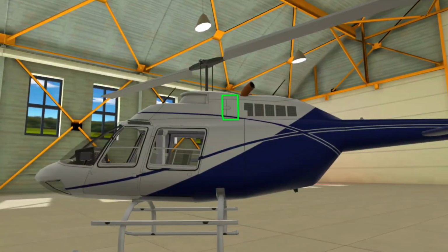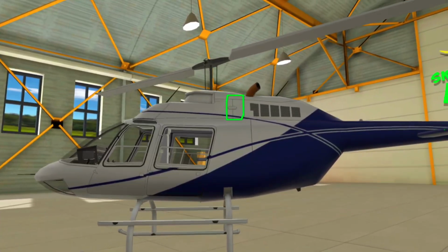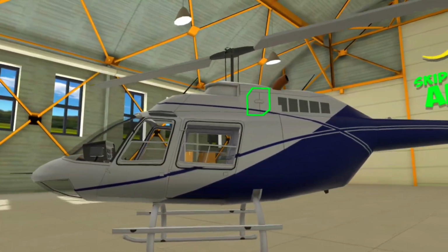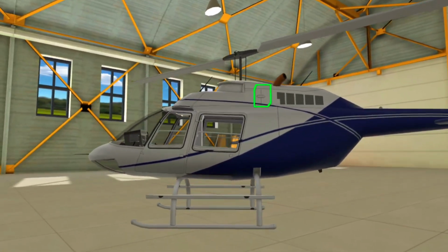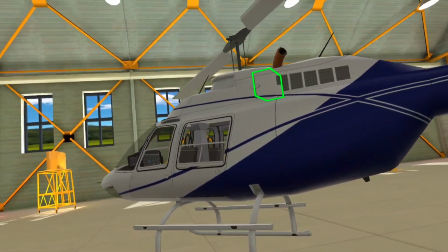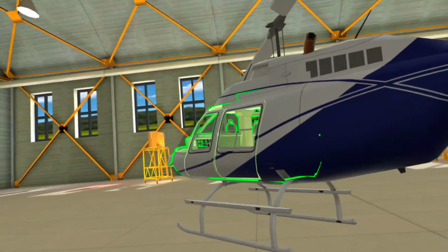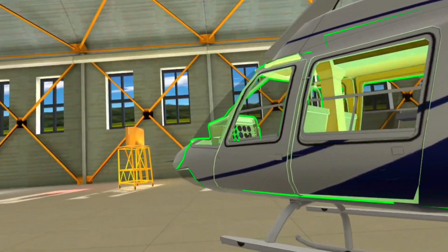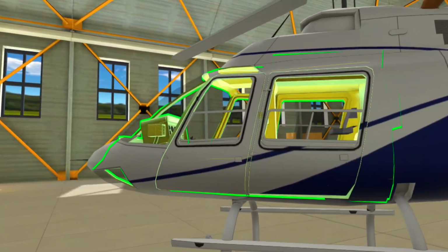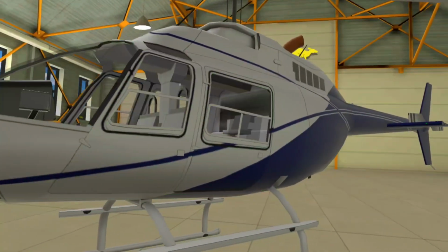The turboshaft engine gets its name because it's designed to power a mechanical shaft instead of producing thrust with a stream of jet exhaust. The engine is rated to continuously produce 650-plus horsepower. It's anchored to the roof just behind the main rotor. Toward the front, there's the cockpit, with essential gauges, navigation aids, switches and controls for the pilot, and the optional dual pilot package.